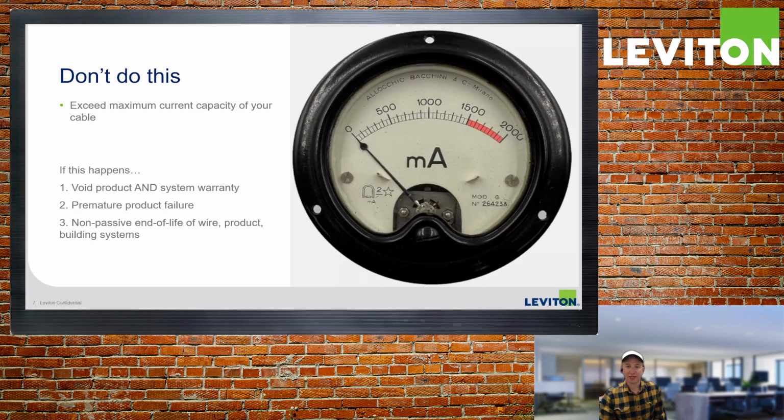Next, do not exceed the maximum current capacity of your cable. We're going to be talking about it today, but every LumaCAN cable has a maximum of 1500 milliamps or 1.5 amps. Do not exceed it. If you do, it will void the product and system warranty. It can result in premature product failure. You also can have a non-passive end of life of wire, the product, or other building systems. We do not like wires getting hot in the wall. We don't support it. We don't allow it.